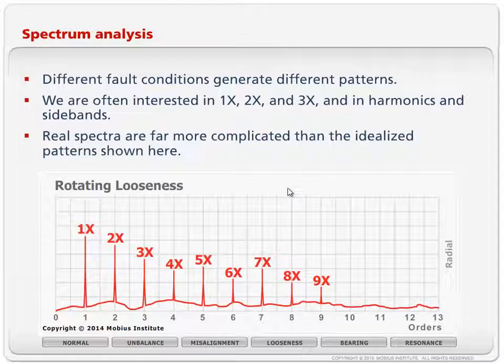But one of the keys is not to get locked into trying to remember patterns. Don't be a wall chart analyst that looks at a spectrum and then looks up at the wall chart and says, that spectrum looks like this sort of fault. What you need to do, in my humble opinion, is become one with the machine. Think about your machines. Think about their failure modes. Think about the technologies that will detect those failure modes. Think about how you should take your vibration readings and where you should take your measurements and so on.